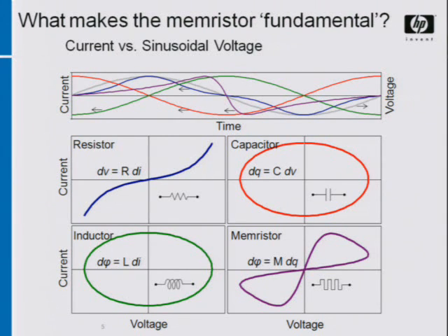Well, what it means is that the device cannot store either charge or energy, but it does store information. And that's sort of the interesting issue about this. And this is also why, in principle, a memristor can be non-volatile. Why it can store information effectively forever, because it doesn't have either energy or charge in it to bleed away, to dissipate with time. All right?